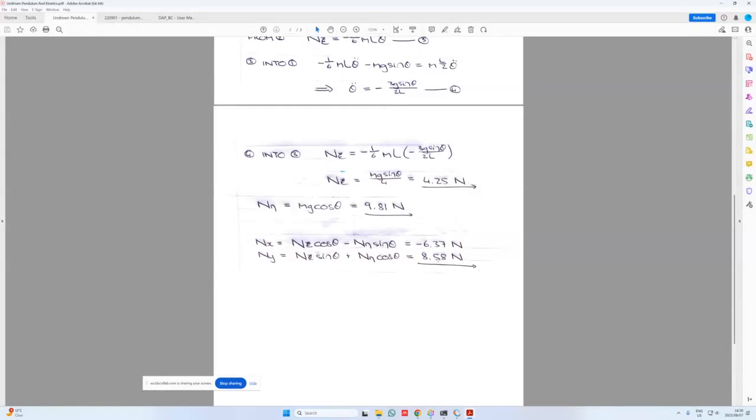In this case, the signs are just reversed, and this is simply because of the IP and the JP indices that I specify in the revolute joints. If I flip them over, I can essentially get the different signs, or I can use the Jacobian matrix and extract the specific sign from the Jacobian matrix, multiply that in, and I should get the correct sign convention in any case. We'll look into that a bit later on, but it's just important to note that from a magnitude perspective, the results that I get over here correlate well.